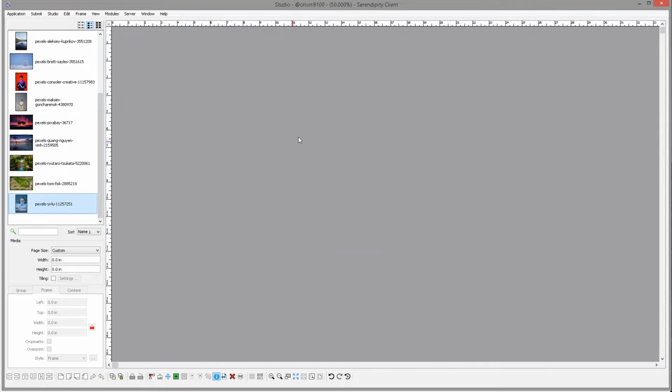Now this has cleared everything, including the page size of our paper in our printer that we're printing to. So if you want to have that show up in the layout area, to make sure you're setting up your template within the restrictions of the paper width, you can go to the media panel and in the width type in the dimensions of your paper. Now I am in inches mode as my measurement, so I will use a 24-inch roll. And you don't have to enter in height because it is a roll, and it will automatically adjust accordingly in the layout area.